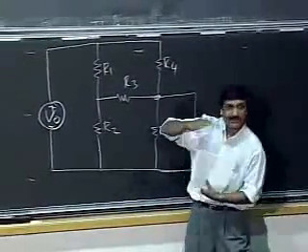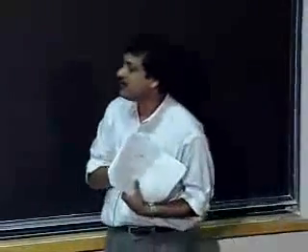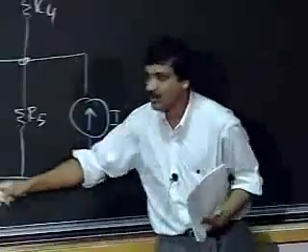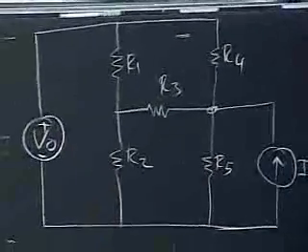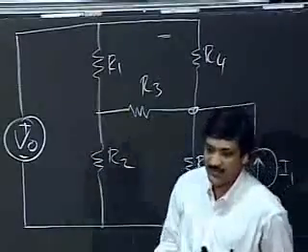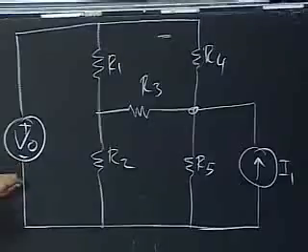Okay, remember, you want to label the ground node with the voltage 0 and measure all the other voltages with respect to that node. Okay, and a usual trick is to pick a node which has the largest number of elements connected to it as the ground node. Okay? And in particular, you will find out later, it's useful to pick a node to which the maximum number of your voltage sources are also connected.